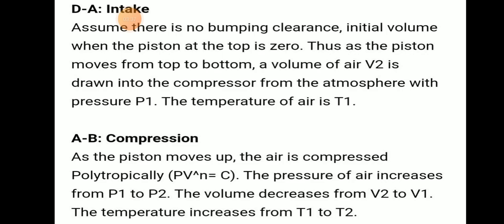Here D to A means the intake stroke. Assume that there is no clearance volume. Clearance volume is 0, so the initial volume when the piston is at the top is 0. As the piston moves from top to bottom, from TDC to BDC, a volume of air V2 is drawn into the compressor from the atmosphere at pressure P1. Then the temperature of the air will be T1.